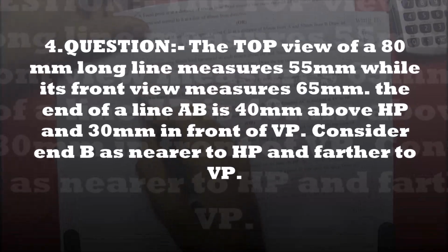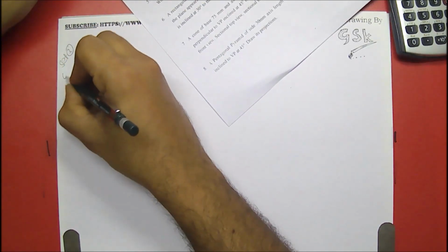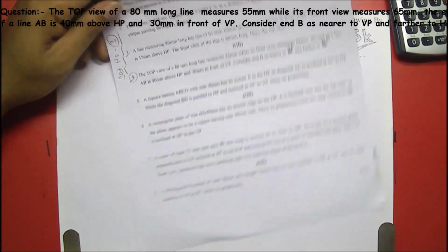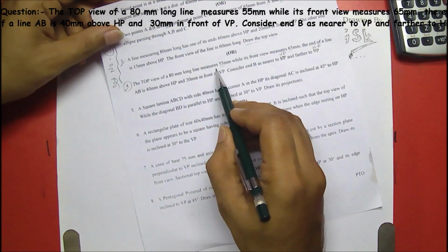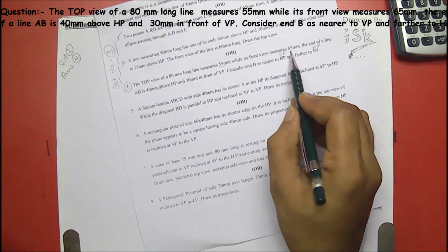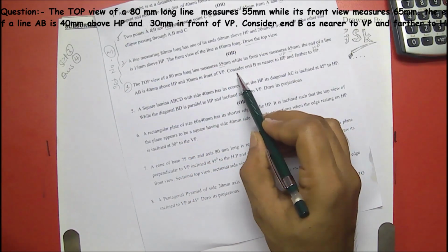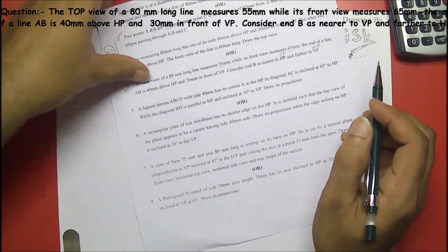Now we are going to discuss the fourth problem. This is set 3, question number 4. Let me read out the question. The top view of a line, 80 mm long line, measures 55 mm, means the top view is 55 and the front view is 65. The end of a line AB is 40 mm above the HP and 30 mm in front of VP. Consider end B is nearer to the VP and far from the HP.